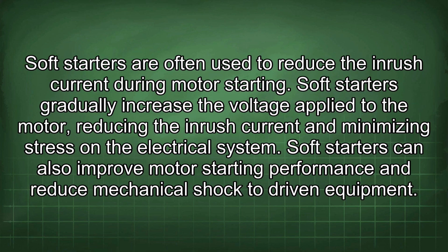Soft starters are often used to reduce the inrush current during motor starting. Soft starters gradually increase the voltage applied to the motor, reducing the inrush current and minimizing stress on the electrical system. Soft starters can also improve motor starting performance and reduce mechanical shock to driven equipment.